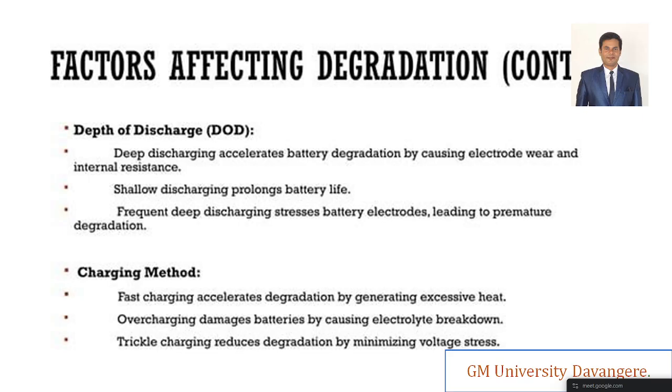So if it is fully charged, then you should go for the fully discharged, right? If the depth of discharge is 20%, it will lead to shallow discharging, and it will also prolong the battery life. So that is the reason, right? Once you charge, you have to discharge properly.